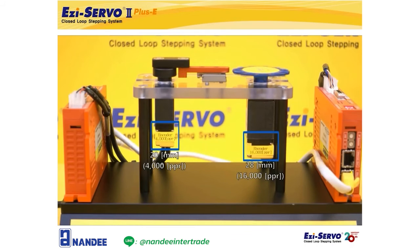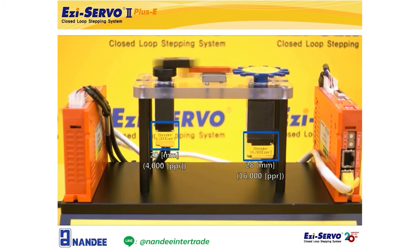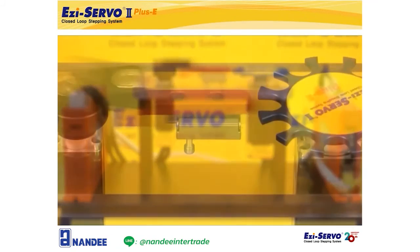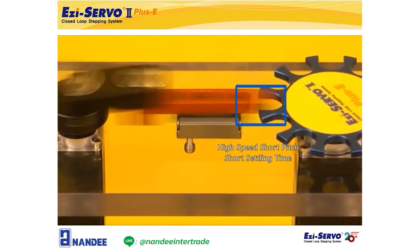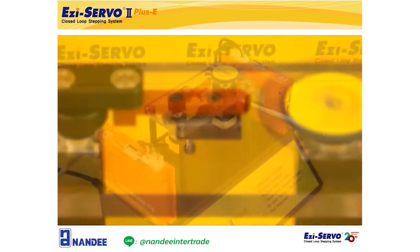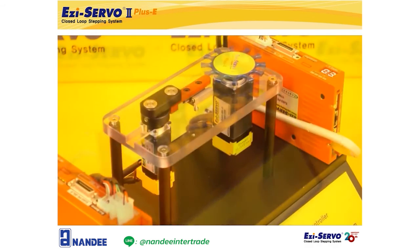Our products provide high resolution of 4000 ppr and 16,000 ppr even with small-sized motors. Due to the characteristic of the stepping motor, it can stop precisely at the command position without hunting even if it moves quickly over a short distance due to its high holding torque.